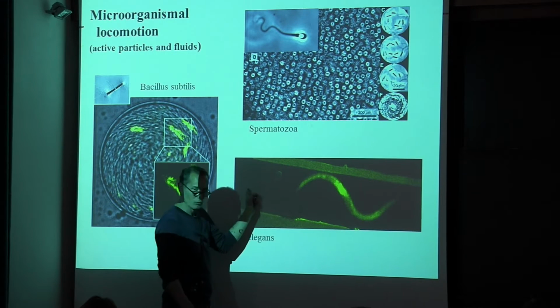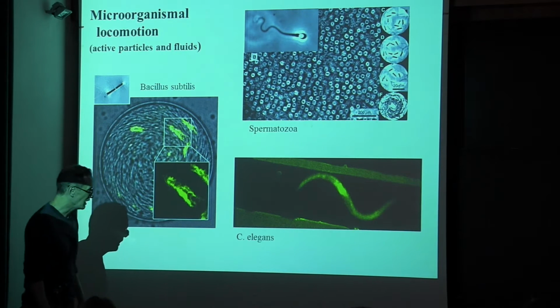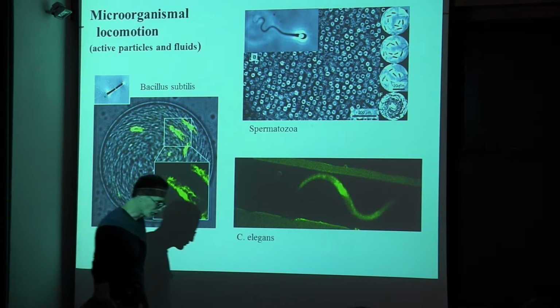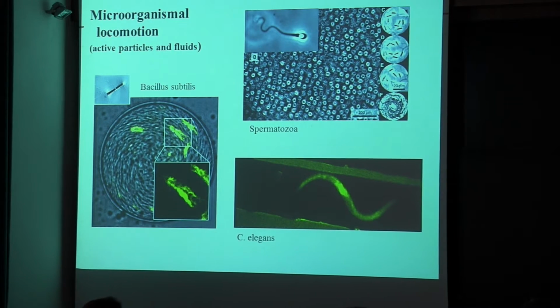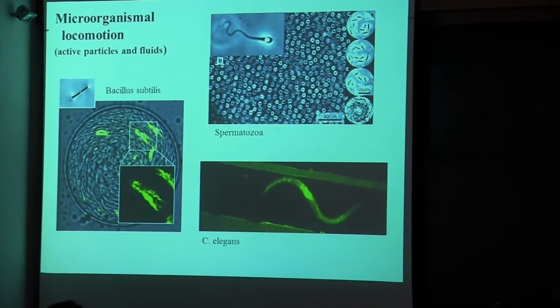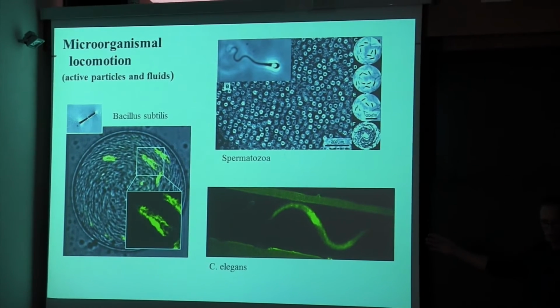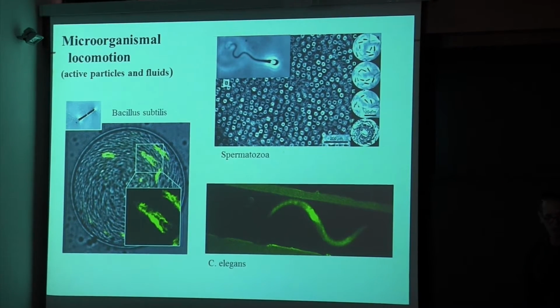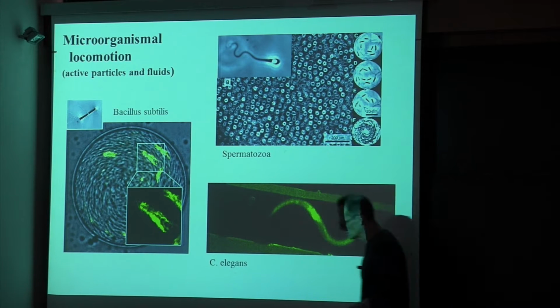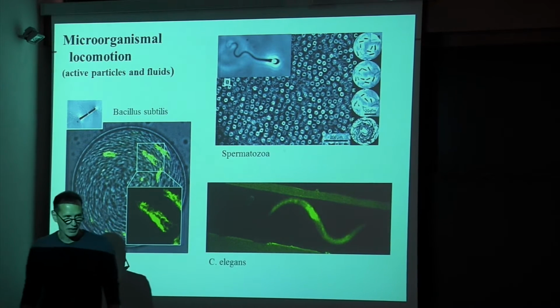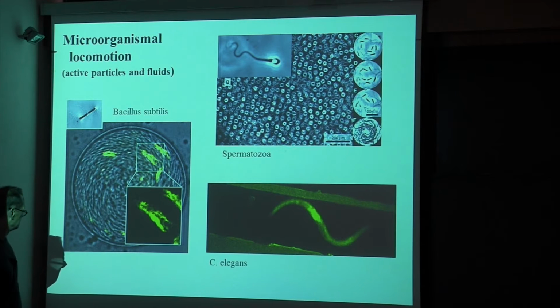way propels itself forward. And someone asks, when can you start using the low Reynolds number flow approximation, namely dropping inertia? This is about an order 1 Reynolds number, and it's pretty well described by the Stokes equations, actually. So order 1, 0.1, something like that, it's good.